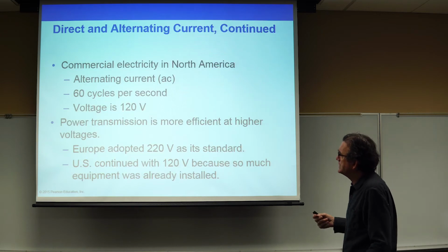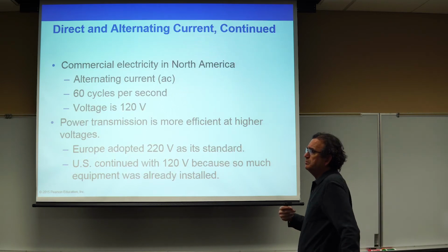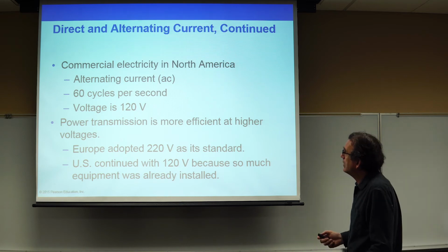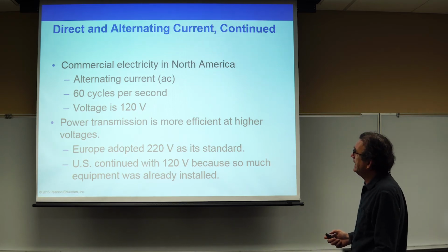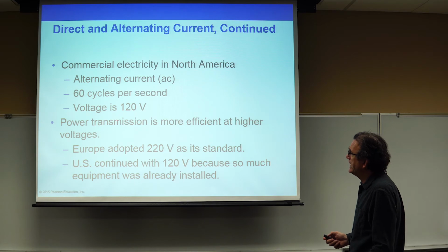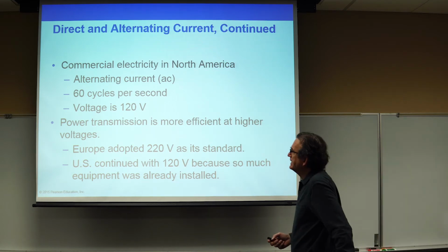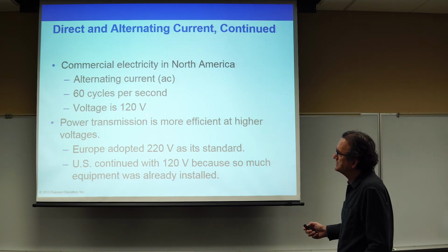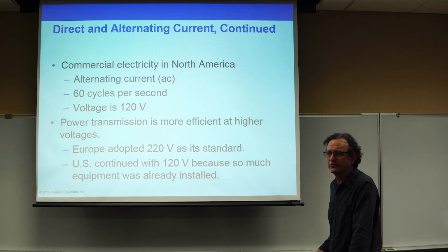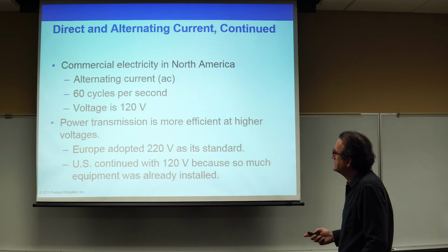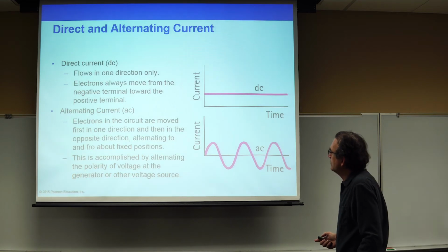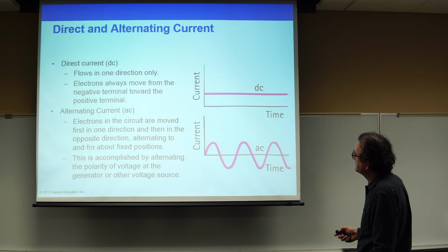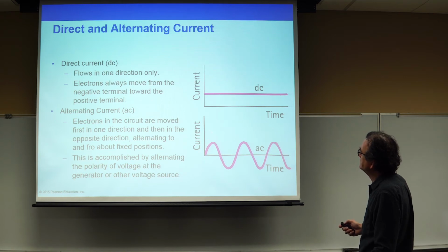Now, as we've stated before, when you plug your device into the wall, you are basically looking at an oscillating voltage source that varies by 120 volts. Actually, this is a little bit incorrect. The reason I put this here is because everyone is familiar with 120 volts. But the actual waveform that comes out of the wall, if this was voltage instead of current, would go to 170 volts, down to minus 170, up to plus 170, down to minus 170.